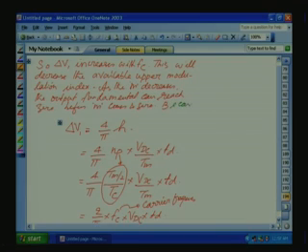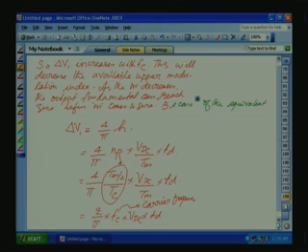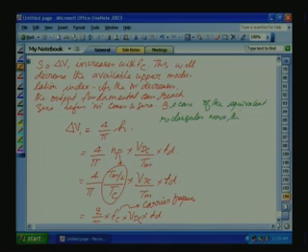Also, because of the equivalent rectangular wave introduced due to dead time, the output current contains the low order harmonics such as fifth and seventh.